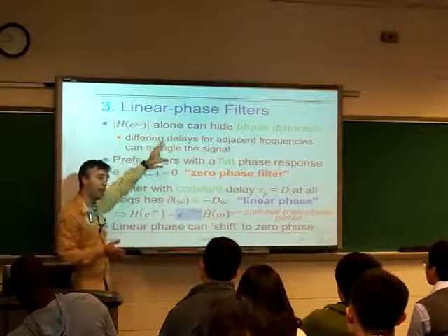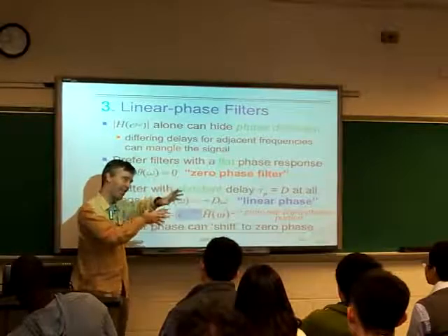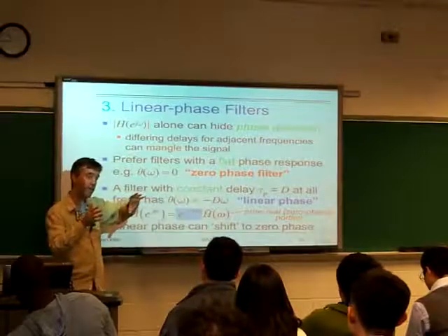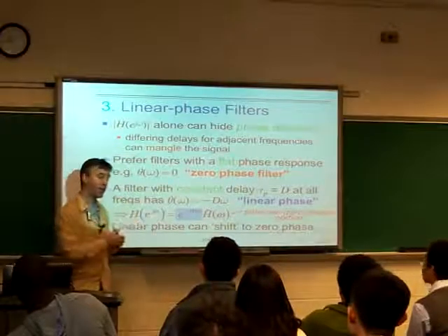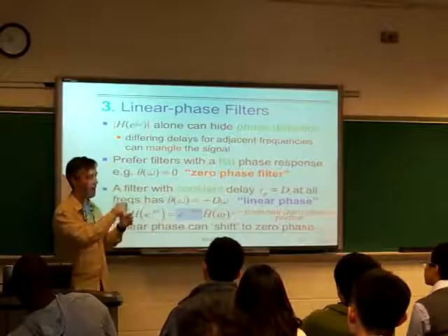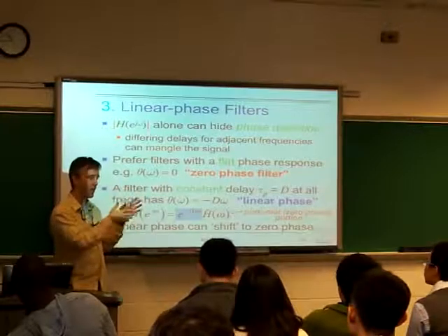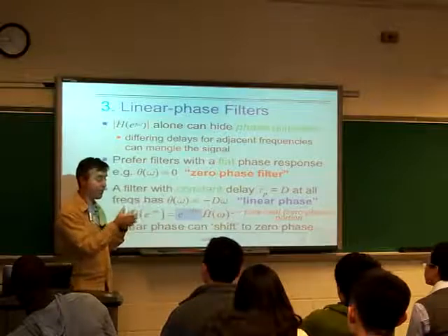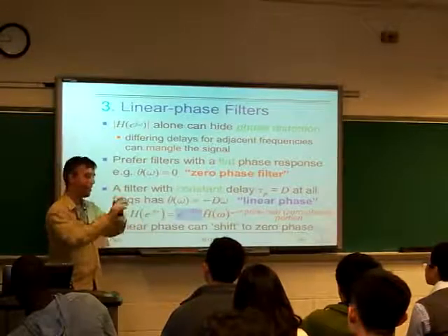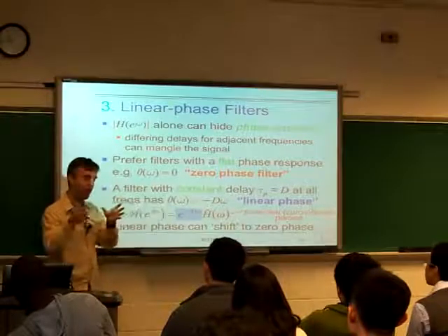If we don't have that, hopefully in the lecture I didn't deliver, which I gave you the video of, we talked about different kinds of delay that the systems can impose, phase delay and group delay. Group delay is this idea that as you change in frequency, the phase changes by some linear function of frequency, by some slope, then a set of frequencies in that region, corresponding to an envelope, will experience a delay.